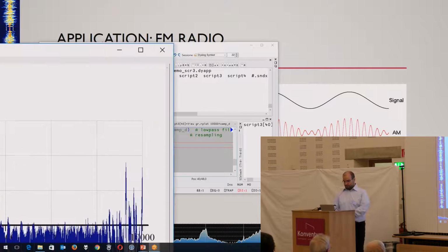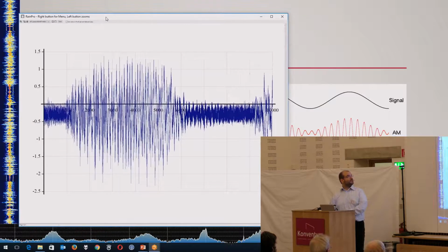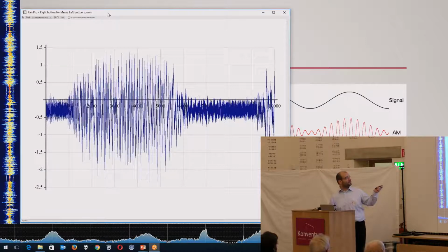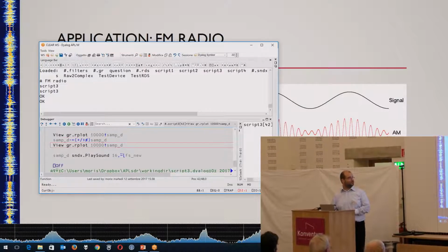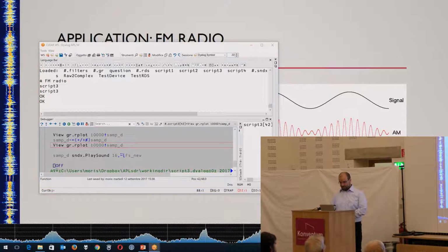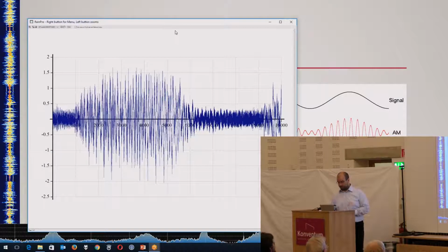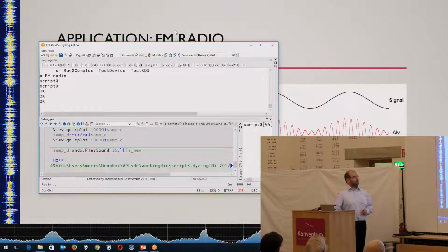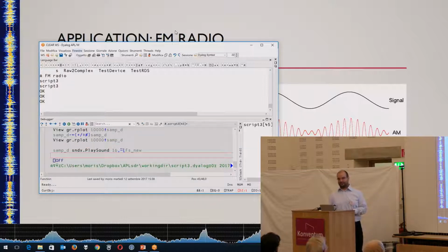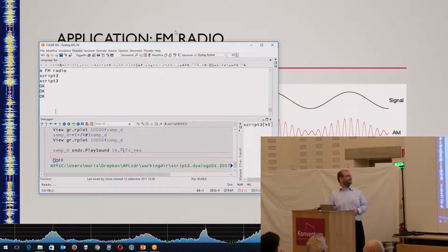Yes, just one more thing is that there is this effect sometimes. It's called DC offset, where the signal is centered about something lower than 0, but that's very easy to correct, of course. It actually makes no difference for the speaker itself, but it might for some applications. And I hope... 5 seconds of radio I recorded at home. It works. Okay.